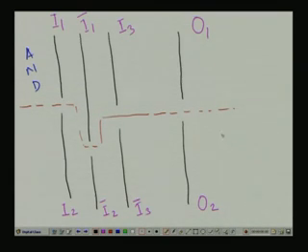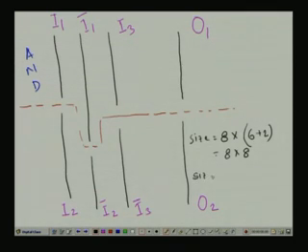8 product terms, 2 to the power 3, 8 by 6 plus 2. Because 2n means 6, plus 2 outputs. So, the actual or original size should be 8 by 8 structure, whereas here we see that the product terms we are not sharing. So, rows are the same, and the modified size will be only 8 by 4, because here columns are only 4.